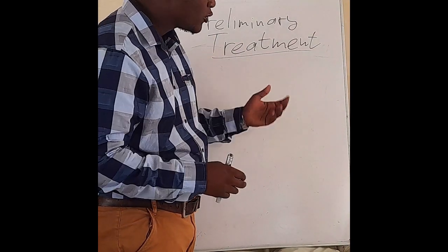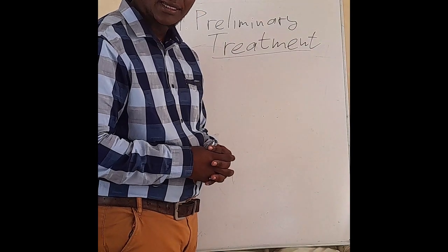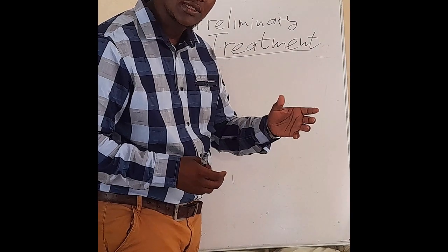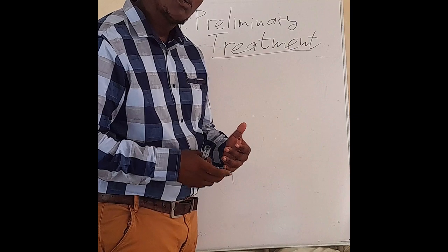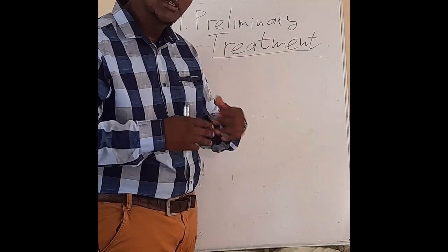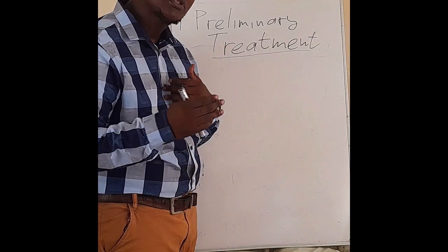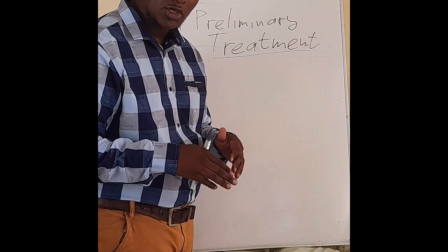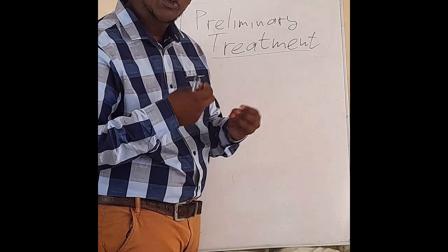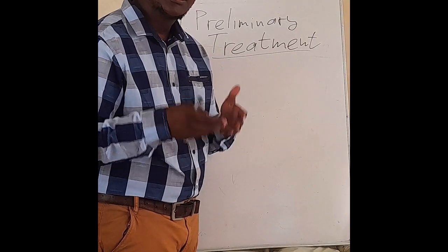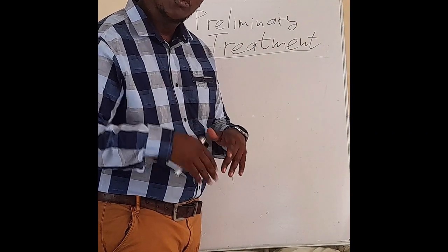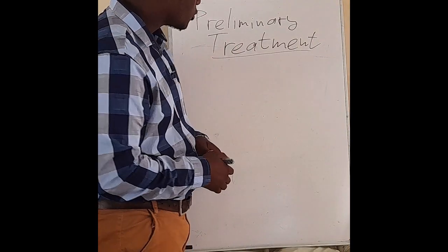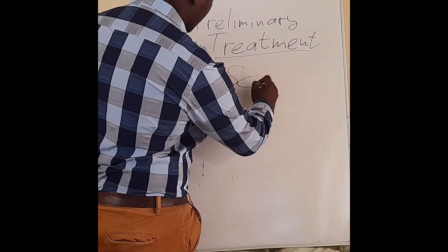And then lastly, under preliminary treatment, we'll have our grit channels. Whatever solid particles had escaped through the screenings will end up in those grit channels, and basically they are long, narrow channels. The reason for that is to keep the velocity of the water quite low, so that the solid particles in suspension that passed through the screens are able to settle down before the water goes to the following water treatment stage. So let's start off with the screens.